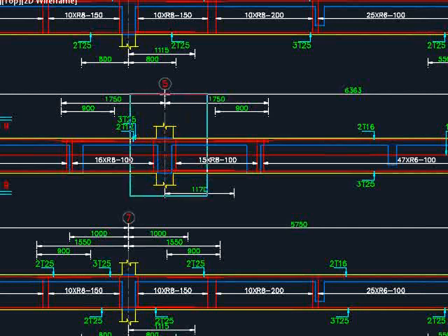As for the intermediate support here, you will expect the main reinforcement bar here at the top of the beam, and you will need to indicate where this main reinforcement bar has to reach, so that the supports resist with good stability. This will be dependent on the bending moment diagram, especially at the support, which in this case a lot of reinforcement bars are required, and indicate where it should stop.